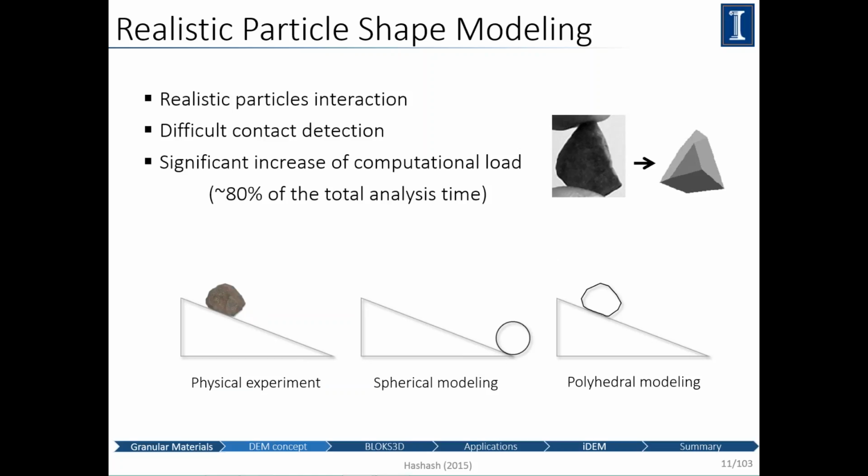And that makes a big difference in our ability to capture the underlying mechanisms that relate to the interaction of the particles. When you are dealing with spheres, you have to make so many approximations. You sometimes have to fuse spheres together. People have done that to capture, say, the shape of your particle. But from our basic understanding of granular material, we know that particle shape controls its behavior, in addition to, of course, the frictional properties. And therefore, the discrete element work we've done does that.